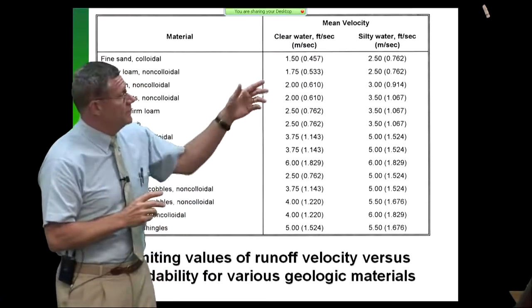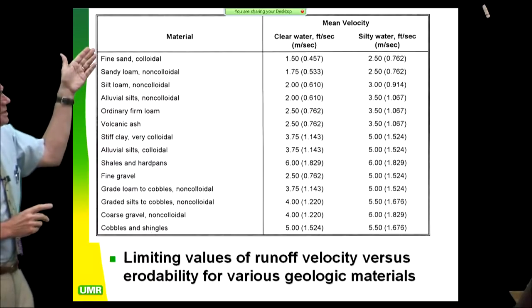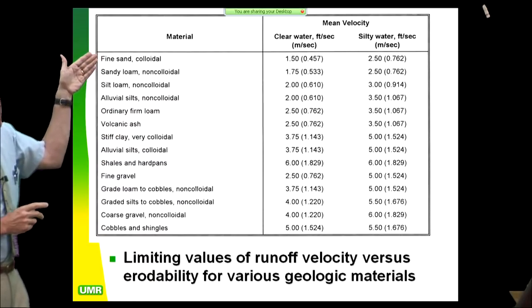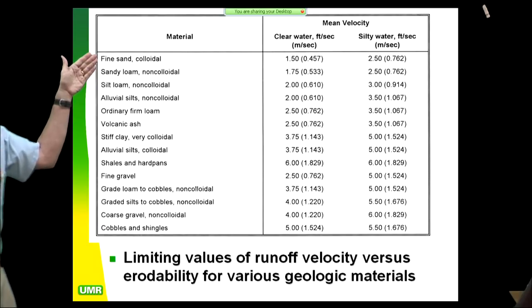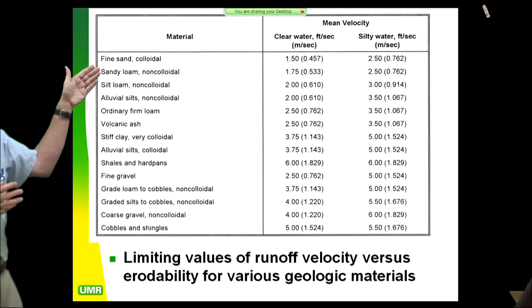And what you have to have here is clay. So if you come over here and look at these different materials, sand doesn't have a lot of resistance to erosion. It doesn't have any cohesion. It's a frictional material, nice clean beach sand, about a 33-degree phi angle of internal friction, no cohesion. Sandy loam is going to have a higher apparent cohesion and a higher apparent friction, and as long as it doesn't get saturated, it can do quite well.